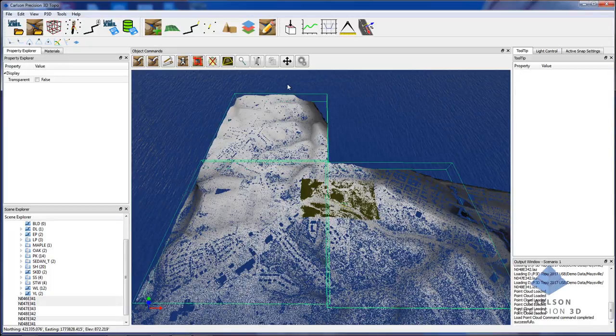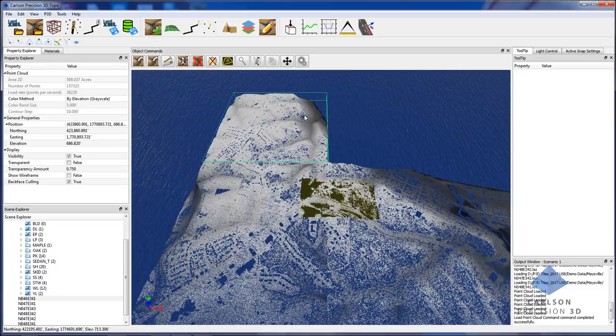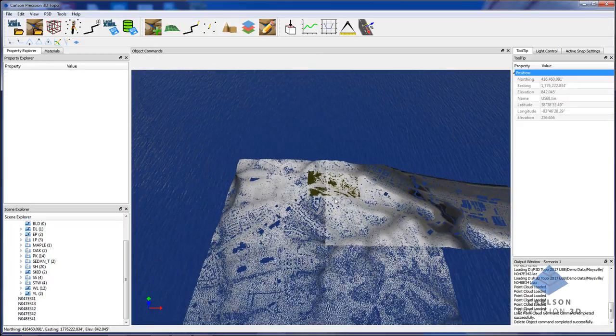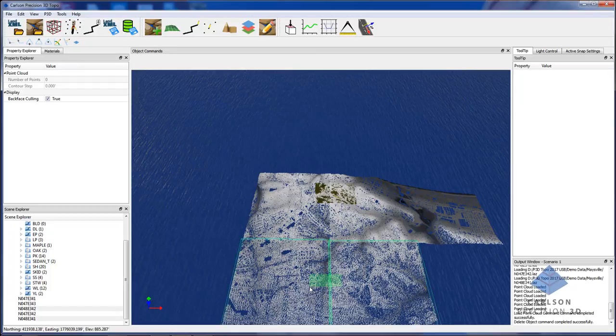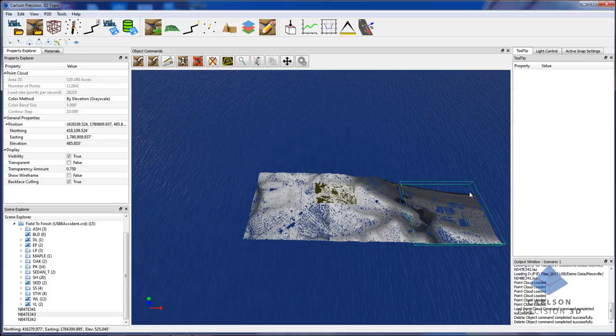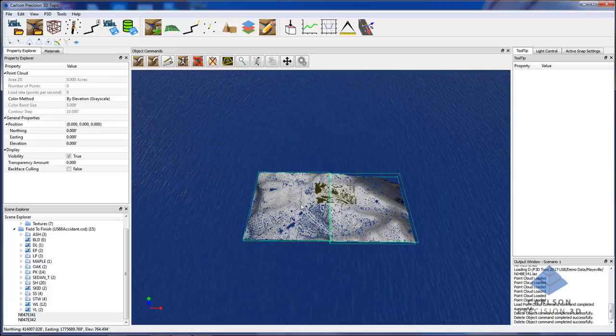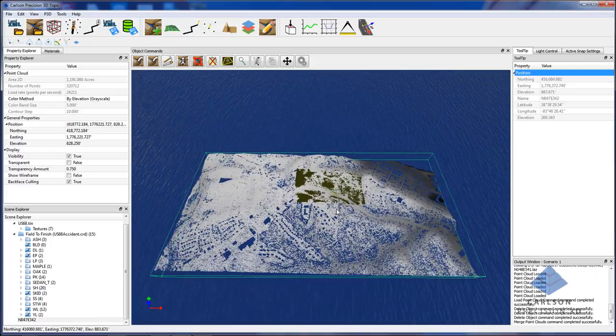And I think in this case, what I want to do is get rid of that one because I can see I don't need it. I'm just doing a right mouse button click and dragging to the left, which is a crossing selection set. I'm going to just pick on this guy out here and delete that one as well. And what I'm going to do is select these two at a crossing. I'm going to use our merge command, and I'm going to merge those point clouds together.